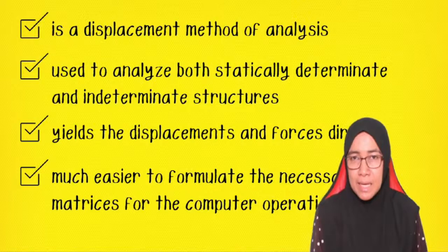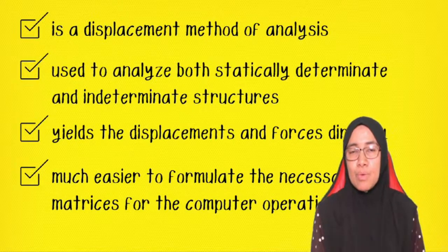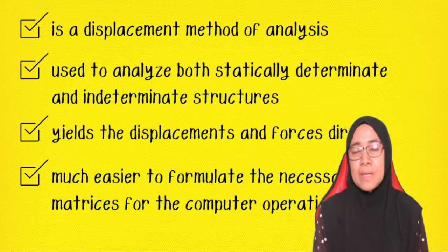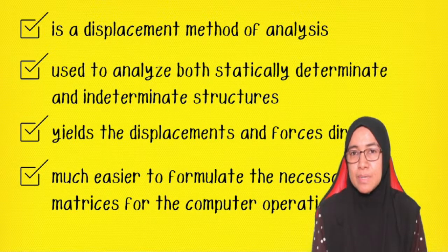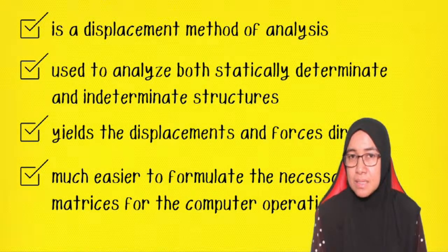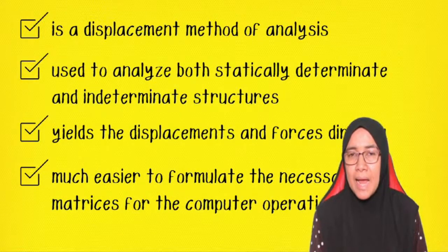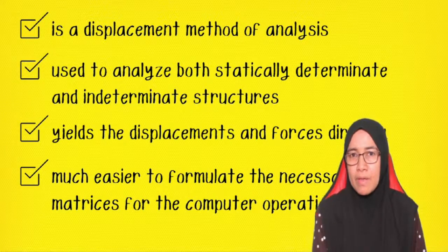Okay, stiffness method is also called the displacement method, because displacement is the first output. Remember, we will solve for the displacement by solving the stiffness equation, or force-displacement equation. Okay, in truss analysis using the stiffness method, we can analyze both statically determinate and indeterminate structures, and this is one of the advantages.